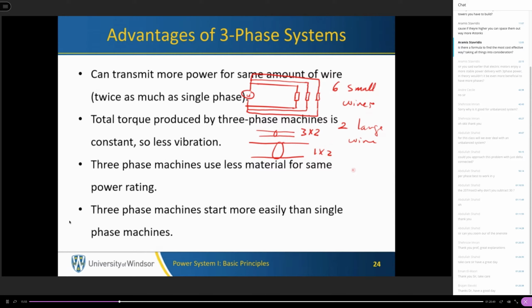But in 3-phase systems, you can connect the load as star connected and use all the 3 wires. If the load is balanced, you don't need a grounding wire. Even if we connect a grounding wire, the maximum number of wires needed to serve the same load is 4, as opposed to 6. This is the benefit: we save the amount of wire needed to serve the same load.